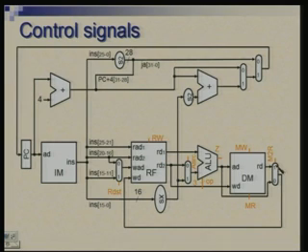okay. And then another multiplexer here which is distinguishing between what goes to register file, whether it is from memory or from ALU, all right. So, memory to register file M2R. This is called P source, PC source basically, either here or there. Then whether it is jump instruction or not, so another control signals. So, these are the control signals.